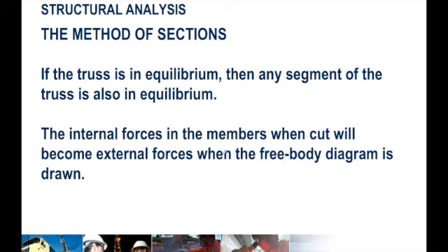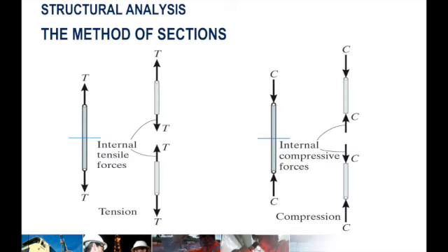So the internal forces in the members when cut will become external forces when the free body diagram is drawn. So this is what will happen. If you have this member acted upon by a tensile force, this is just an imaginary plane that you pass through the member, and that's what we call cutting the member.